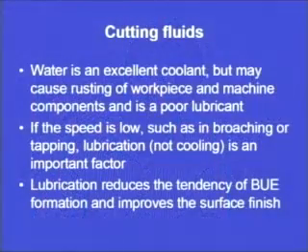Now, what type of coolants or lubricants should be used? Water is an excellent coolant. If we do not find any other material, we can directly use water as a coolant, but it will only perform the cooling action. We have seen that there are two important functions for the cutting fluid. We can use water as a cutting fluid, no doubt, but it has only one function, that is the cooling action. If we want a lubrication action also, then we need to add certain oils to water to form an emulsion which will serve both our purposes. It will act as a coolant as well as a lubricant.